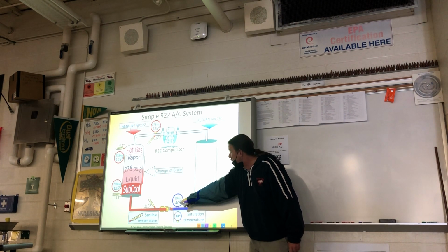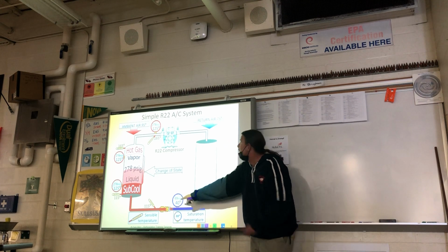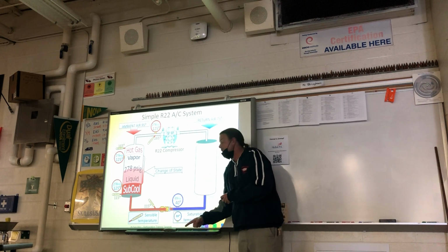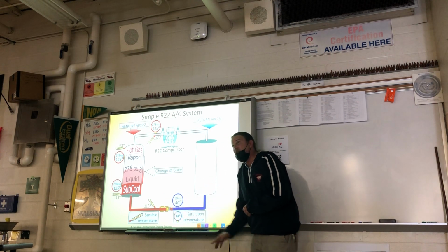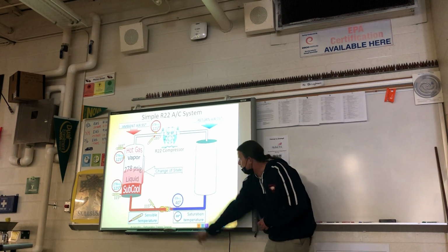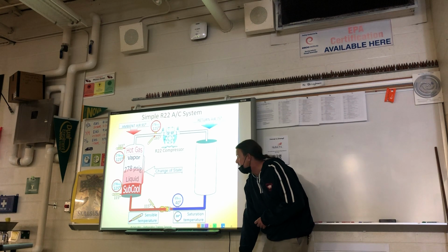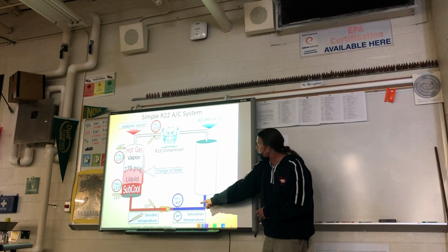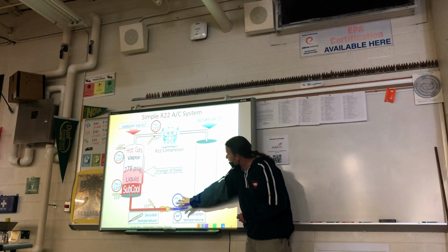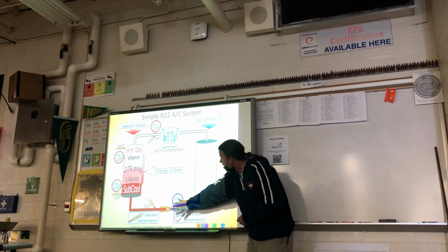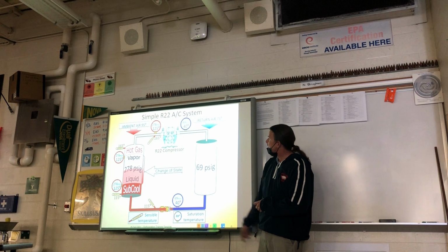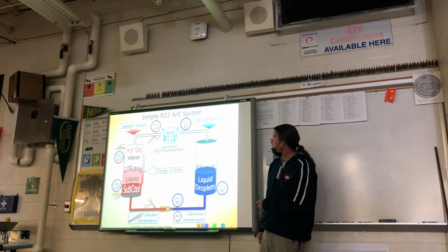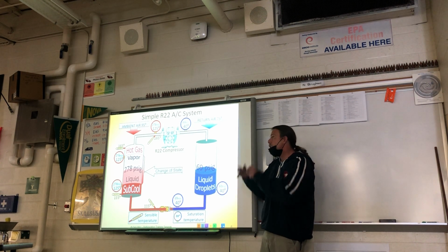And this corresponds right here, 40 degrees, with this pressure of R22 refrigerant. So if I had R134A refrigerant, this could be down to 25 degrees, 0 degrees. But the pressure is going to be lower on this side. Okay? And then what's it doing? It's got about 75% liquid and about 25% flash gas, and that is going into the evaporator where it goes in as a liquid, droplets, right? Because we want it a round ball.